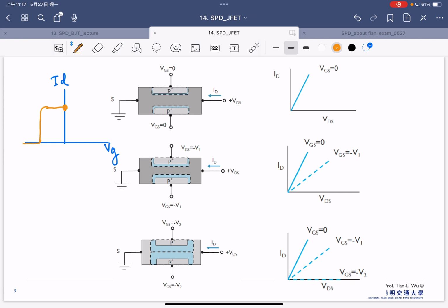And finally we can switch off our device. So our threshold voltage is below 0 volt. And this is already something we have mentioned. This is called the depletion mode, because we need to apply the negative gate bias to deplete our channel here.